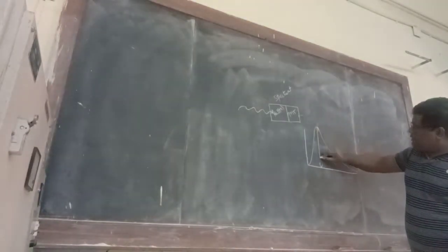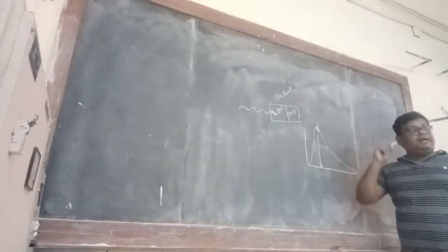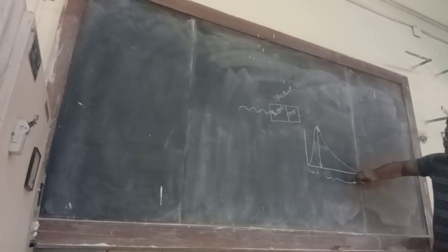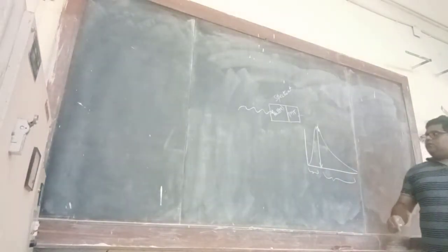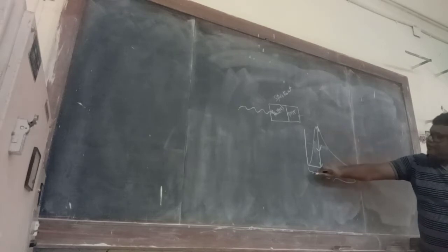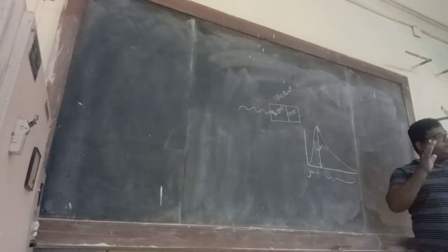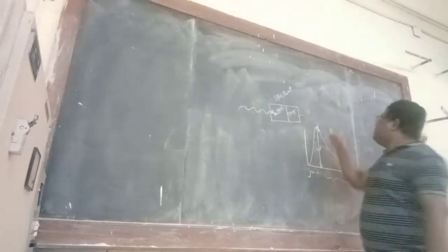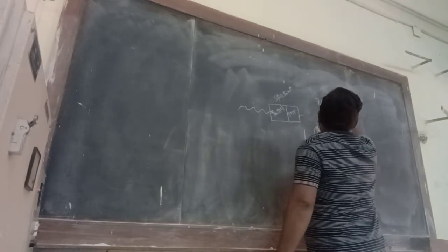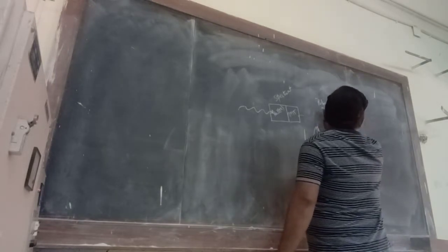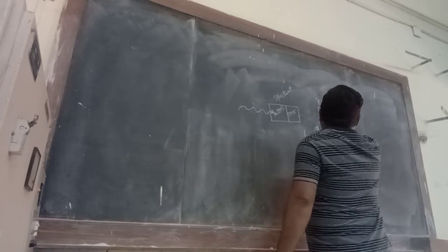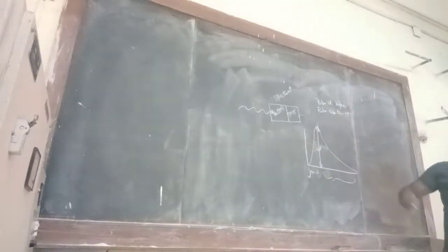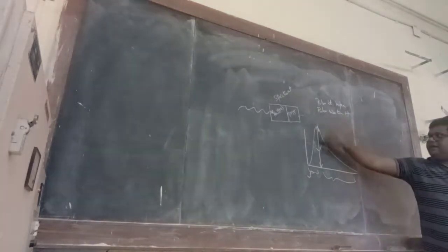But the pulse height is important. Next, the pulse rising time and the pulse falling time. Okay, now these two pieces of information are very important to us, and we would like to preserve these two, the pulse height information and the pulse rise time information. Why? The reason is that what we should actually measure is the entire area.